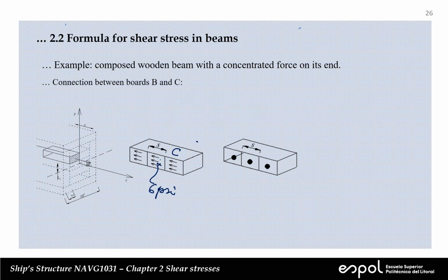But instead of having a continuous contact, okay, we're going to use nails. Okay, so essentially it's the same. So we space the nails every S distance. And originally, we have a distribution of 6 psi on this area, defined with the length of S. Instead of that, we're going to replace that with a single nail.